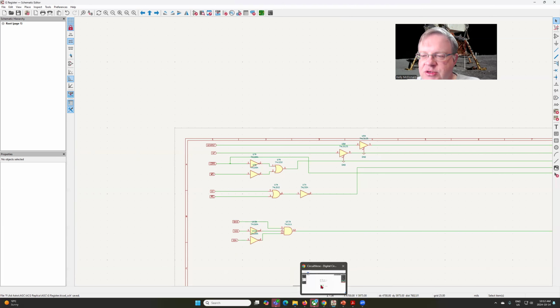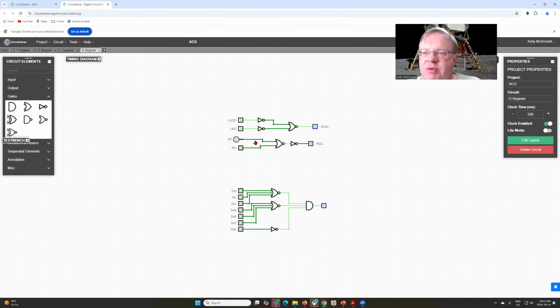If I look at our little simulator here, we can see for our write, if this is set to 0, then we go low here, which is because it's negative logic. That's exactly what we want. If we go 0 here, again, it goes here. So this controls how we can read or write data into the register from the various write lines, either the L register or write lines.